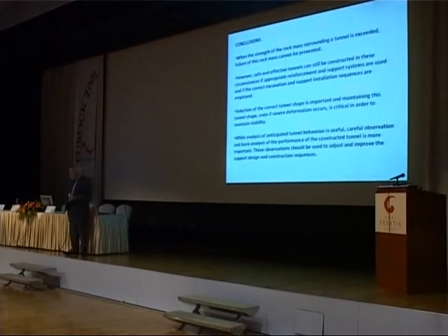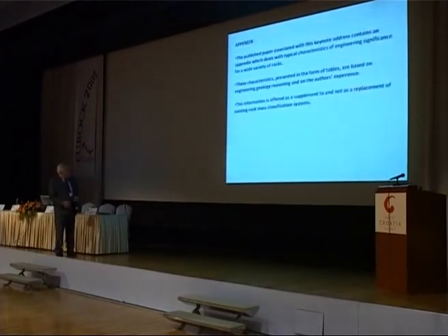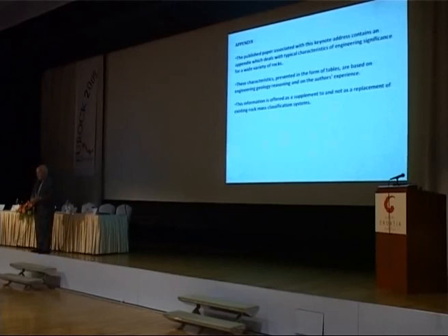And finally, while you can do all the analysis you like, it's the behavior of the tunnel itself that's important, and so monitoring and back analysis becomes an essential part of the design process. This must be a continual feedback loop so that you can incorporate the lessons learned as you progress. And then finally, Professor Paul Marinos, who's my co-author here, and I worked together to add an addendum to the paper, which is just a little addition on some observations from experience of what different rock masses might contain in their makeup.